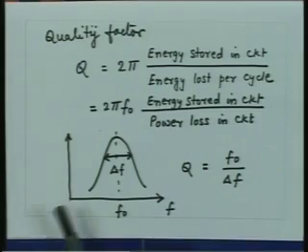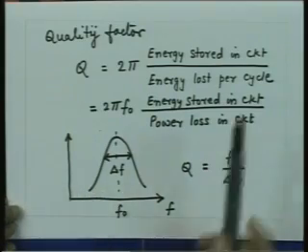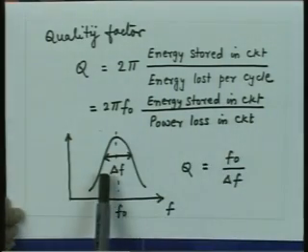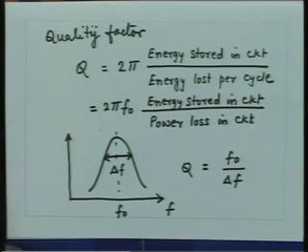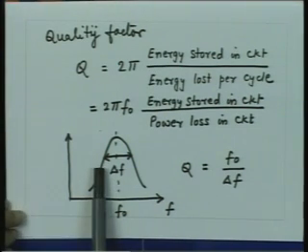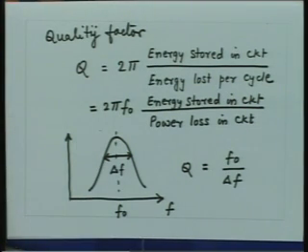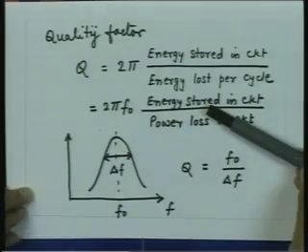So, now the quality factor can be calculated from the impedance calculation, because the impedance can give me the frequency response. Alternatively, take a section of a transmission line, find the voltage distribution and the current distribution on the transmission line, find out what is the energy stored, find out what is the power loss in the transmission line, and use this definition to calculate the quality factor.